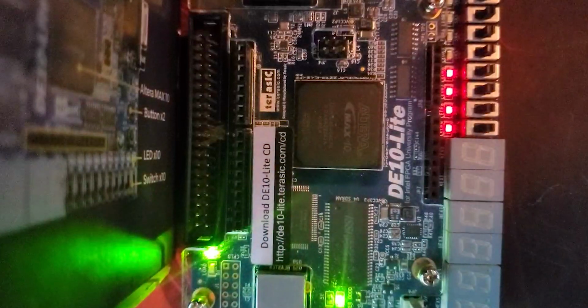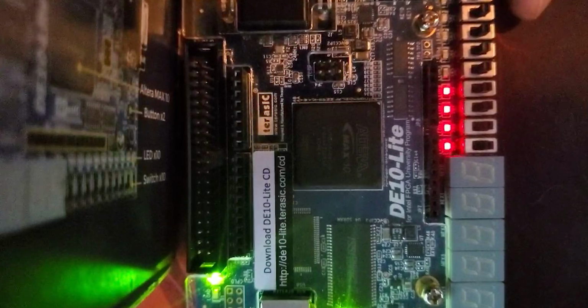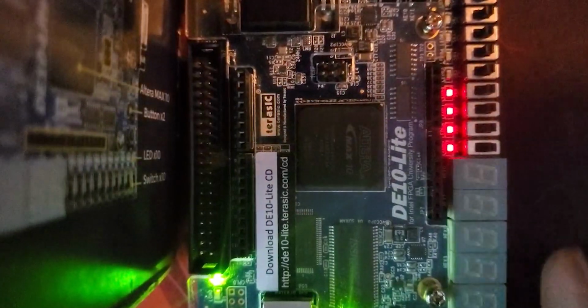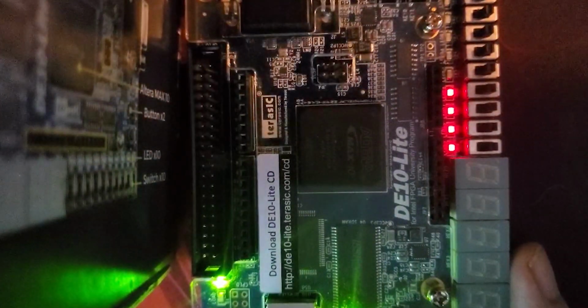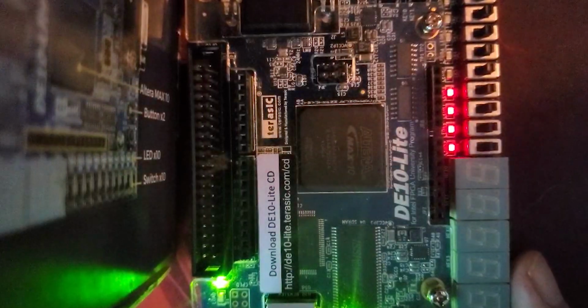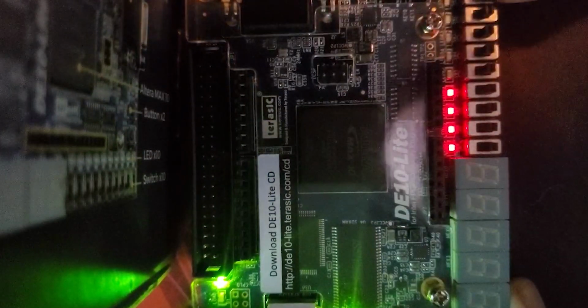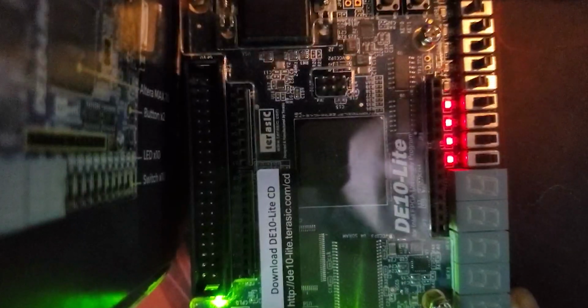Hello, as I promised, we are in the physical part. As you can see, we have the Max 10 FPGA from Intel, and we have already programmed the VHDL code in this FPGA. So basically, this will work as a subtractor. If I introduce 1 minus 1, it will be equal to 0. As you can see, this LED is turned off. But if I put 2 minus 1, it will be 1, as you can see.